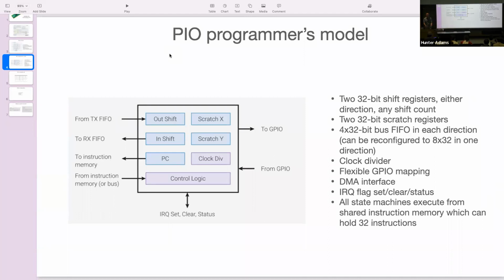And the instructions that we'll look at, that set of 9 instructions, all that those are really doing is moving stuff around among these resources. It moves stuff between the registers, it moves stuff from registers out to GPIO ports, it moves stuff from GPIO ports into registers. It allows you to deterministically, in one cycle, move data from one place to another. And, of course, to apply some logic to it so that you're doing something intelligent with the data that's getting moved around.